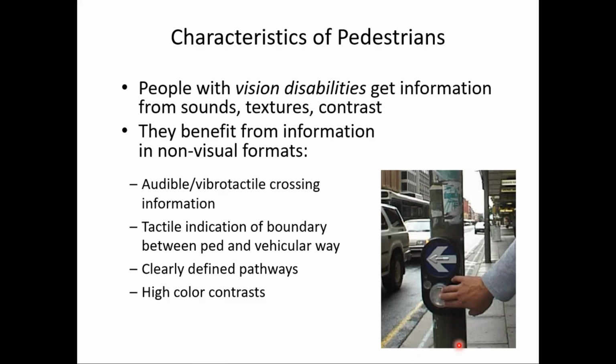In the photo here, we see this is an accessible pedestrian signal, and actually we can't appreciate the key feature of it from the photo, and that is that it has audible tones. There's a locator tone that sounds 24/7 to let the visually impaired know that there is a push button at the corner, and they can home in on that sound and find the push button. And then after they push the push button, at some point the walk indication will come on, and that will be a more rapid tone to let them know that it's okay to cross the street.